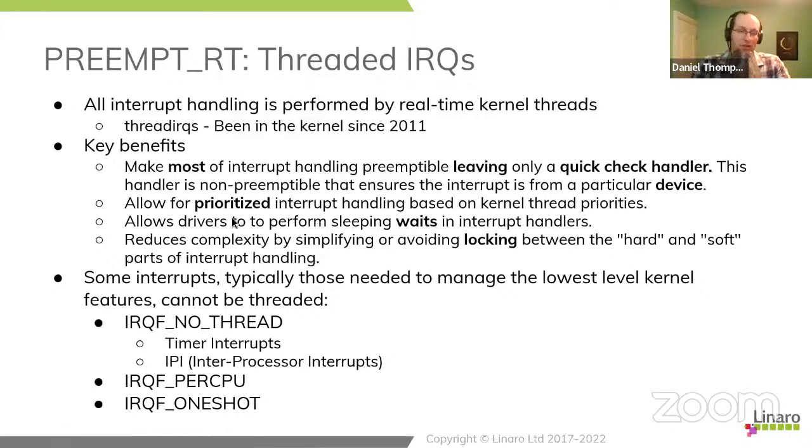Threaded interrupts allow drivers to perform sleeping waits in their interrupt handlers. This is one of the reasons that threaded IRQs are used for things like I2C, because when you're writing a driver for an I2C peripheral, simply reading and writing to its register sets is expensive, and you want to be able to sleep while you're waiting for the results.